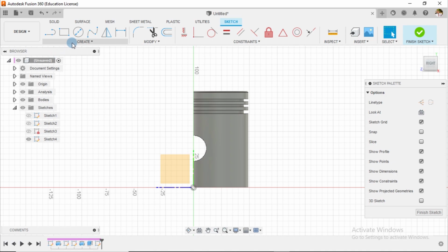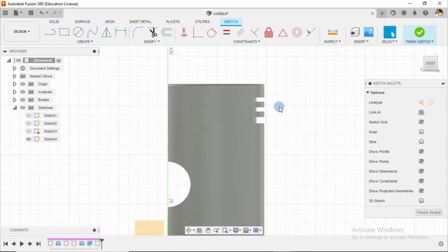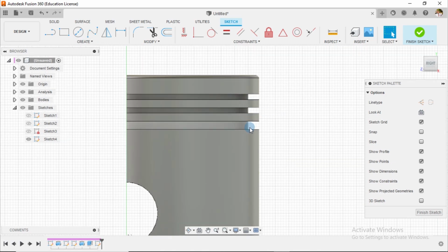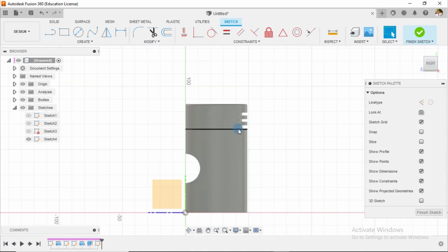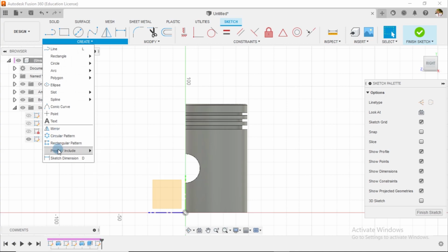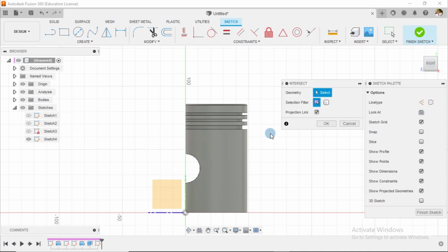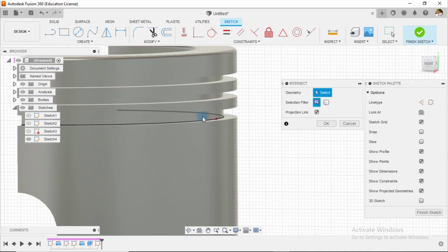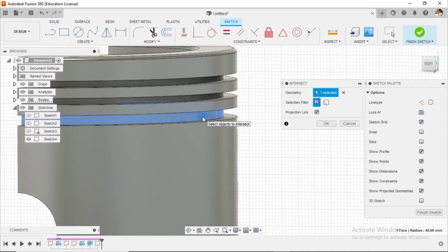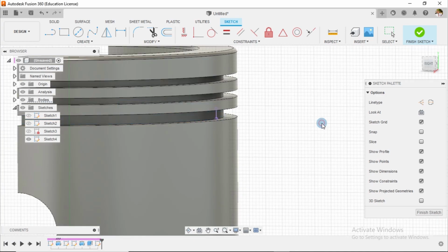So to begin with this, we have just one important thing to do, which is, as taken from detail B, we notice that we have a dimension of 115 degrees, and that dimension is between this line and an imaginary center line. So for us to have those references, we're going to use the intersect tool, and I'll simply select on this face where we have the reference, and I would say okay.